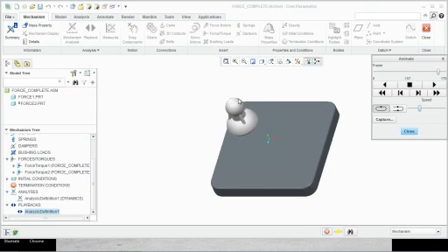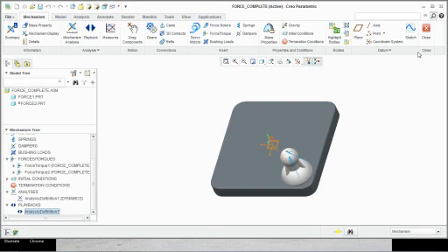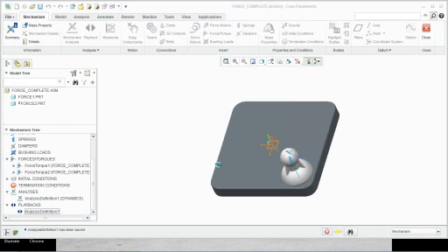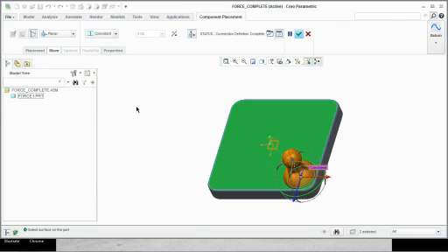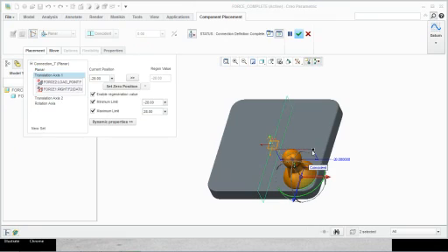Now what happens here is that if you look at the assembly connection, you have a translation axis limit which says it goes from -28 to +28, which is this surface. So that means the connection is not letting it go past it. Now it's here. In that direction is where the force is acting, so it's pushed in that way. If you don't have this limit, it'll just go up. Okay? So the reason it's hitting it here and then going straight is because of this limit which is set. It cannot go more than 28 inches from this plane.